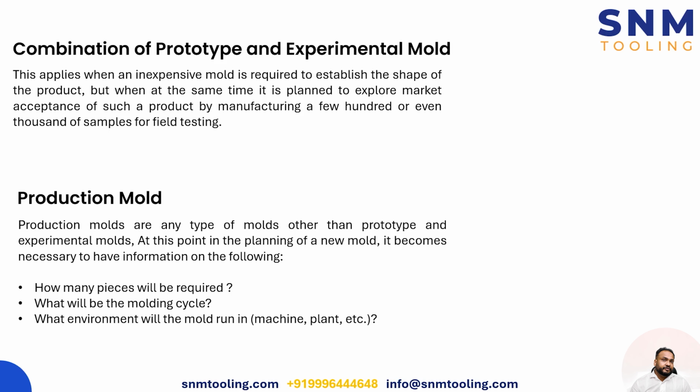Next, what kind of material, whether it will be P20 or S13, that will be dependent on how long the mold will be in service, and what are the conditions the mold will operate in, say, what type of machine the mold will be mounted to, right?